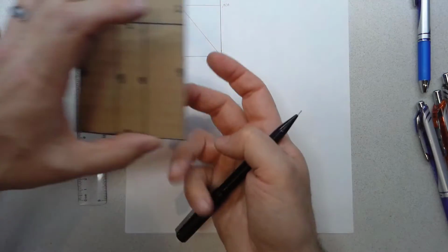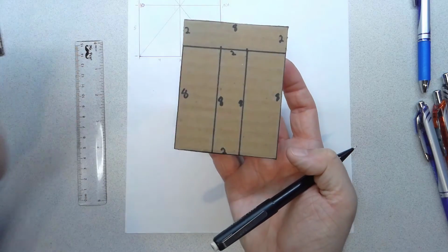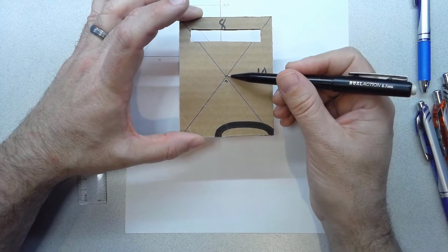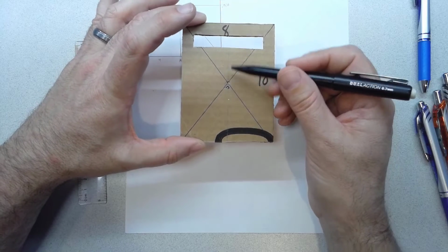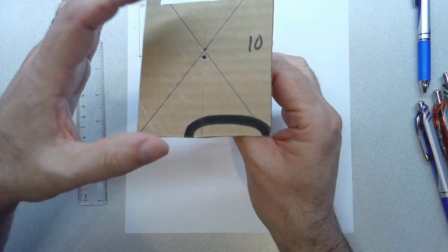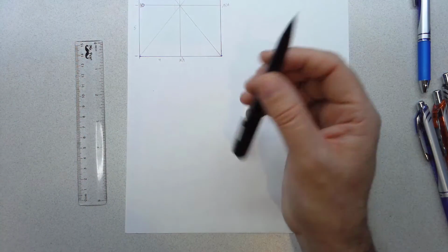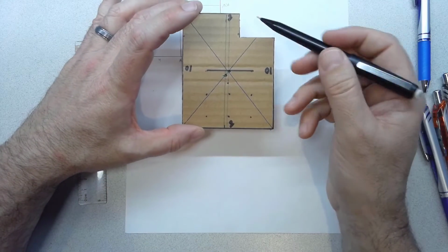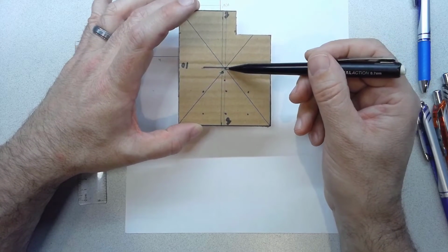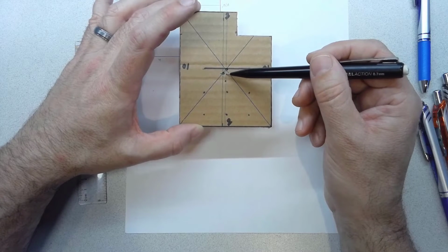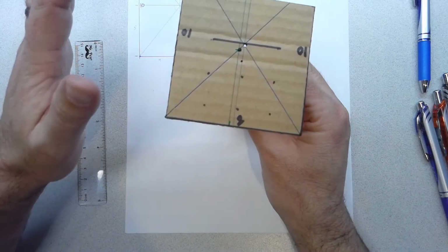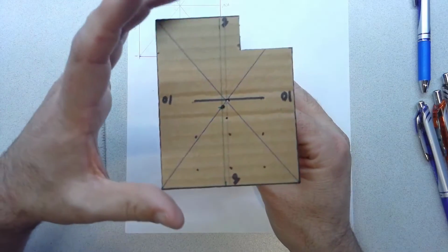So for an original standard rectangle, it's going to be right in the center of it. For our rectangle where we've cut out some on the top, if this was the original centroid, we figured out mathematically it shifted down along that axis of symmetry this much. And so then this one balances nicely right at that centroid. And then same thing on this third shape, the more complicated one, where now we don't have any axis of symmetry in x or y. So our original centroid that was here shifts a little bit this direction as far as y, and a little bit that direction as far as x, and then it should balance again, and it does. Okay, so that's a review of centroids.